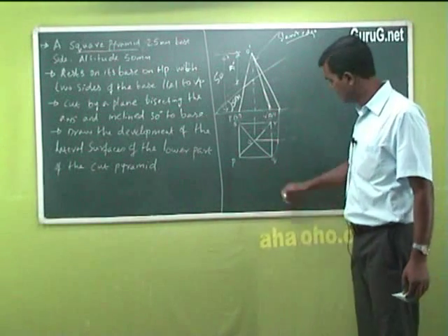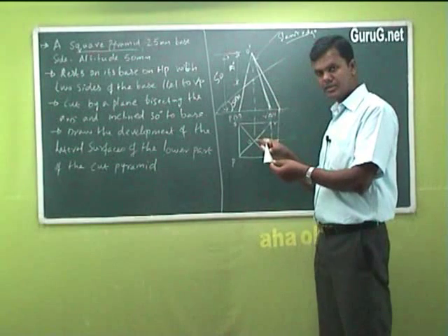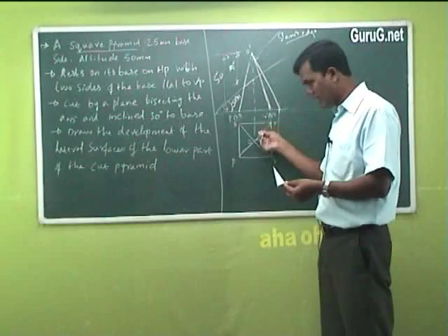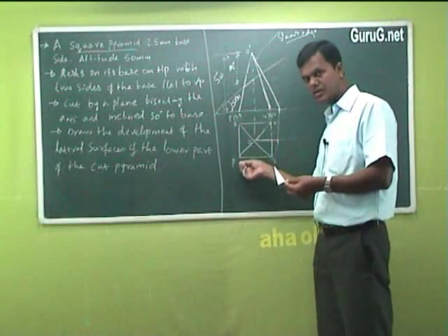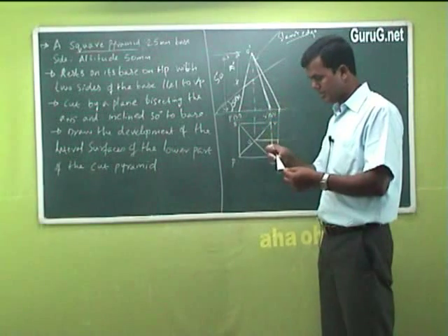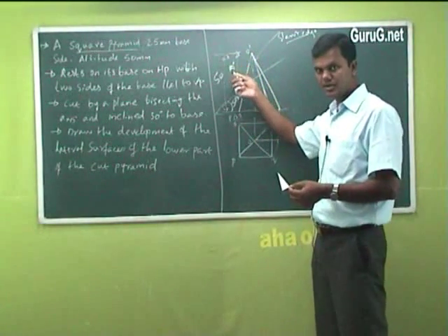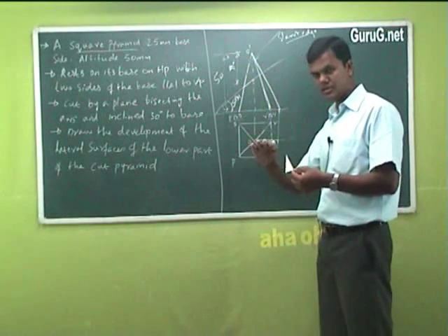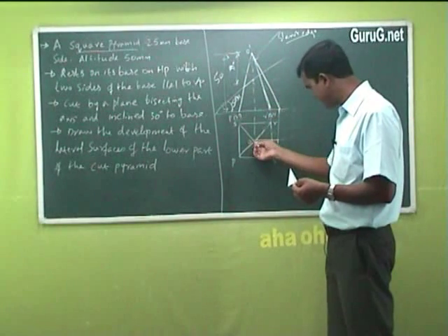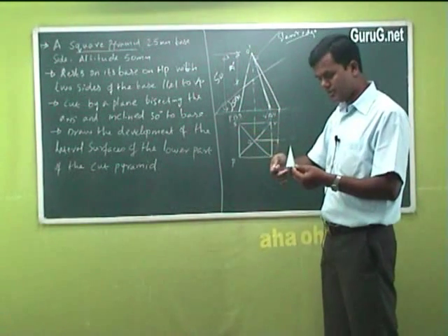Can you understand? It is like this. I mean, a square pyramid. This is the height. I have just shown cross lines. These are your slant generators. They are not actually the true length of the slant generator. It is only the inclined portion, or I can say it is foreshortened. So for the true length, you are making this slant, I mean inclined edge, into a straight edge. So it becomes straight. Right?